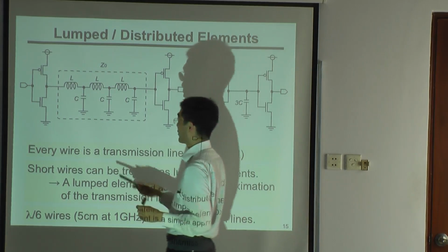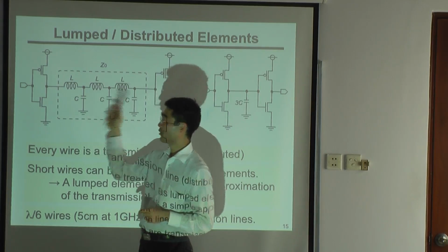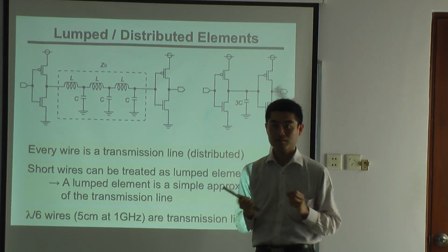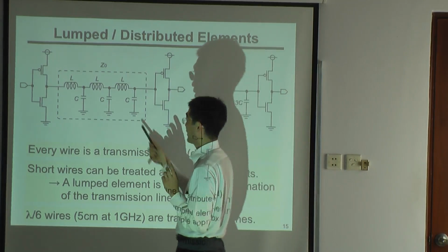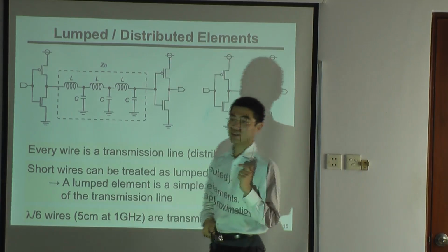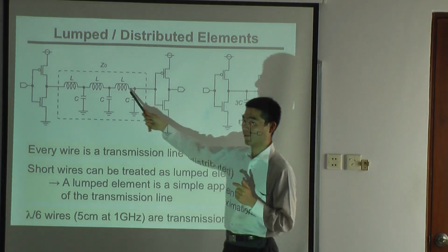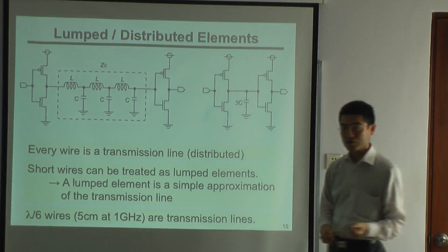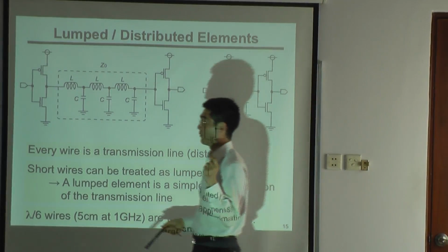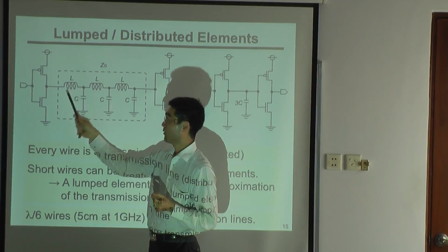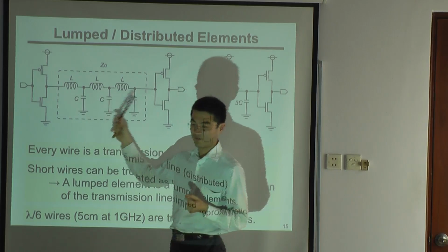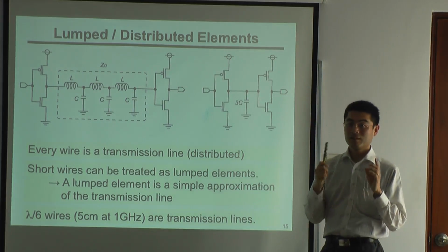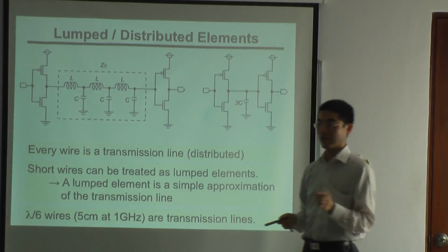So in femtoseconds, it reflects and finally arrives at the steady state. So in this kind of short wire, we can ignore the L and consider that this has only C. But actually, there is L and many reflections, and in the end it goes into a steady state. But the time is so short that we can ignore it.